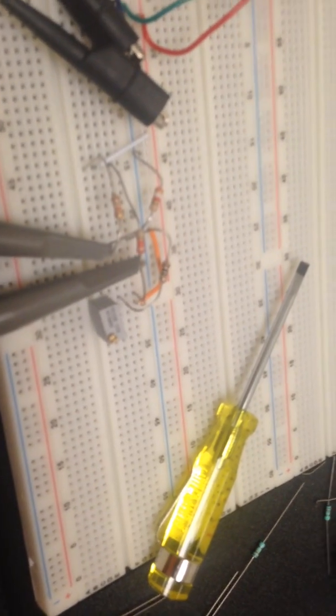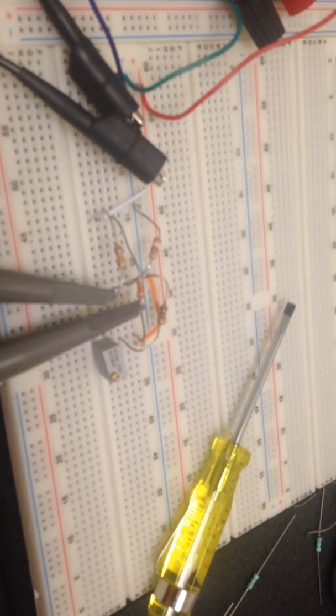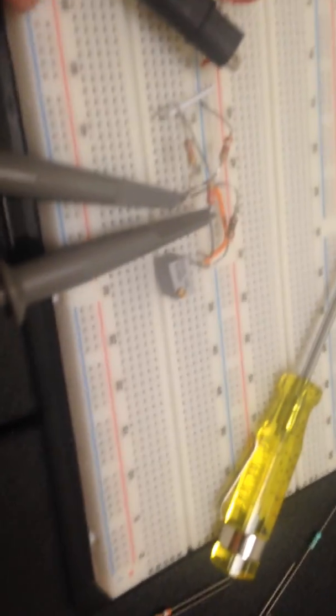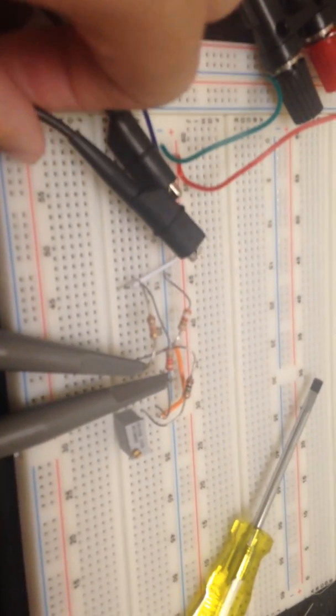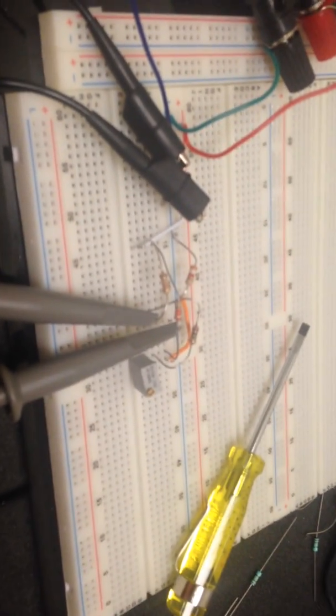It's easy to see on the diagram. That's basically just a potential difference across R3, which is kind of what we're looking for and trying to minimize. And these probes here, they're just attached to ground so that the probe readings are relative to ground, which is important for when you subtract them later.